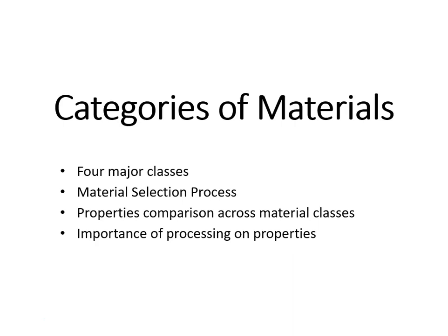Before we get into individual classes of materials, I need to let you know that the main difference in material classes is provided by chemical bonding. Material classes are basically a manifestation of the different types of chemical bonds that are inherent in those different materials. Those include, for those of you who remember your chemistry, metallic bonding, which basically consists of discrete nuclei in a delocalized sea of electrons. So charge is neither directional nor localized.